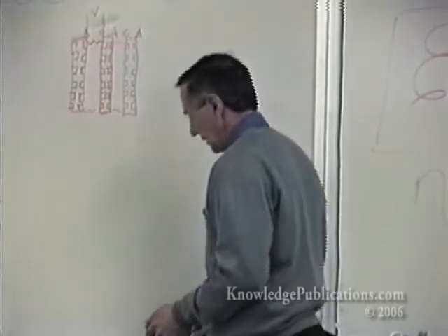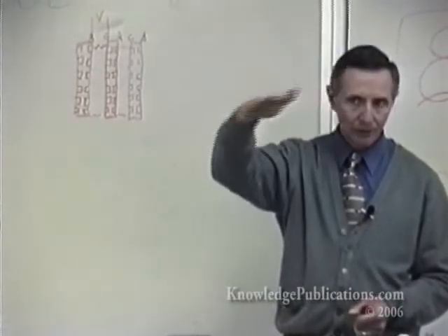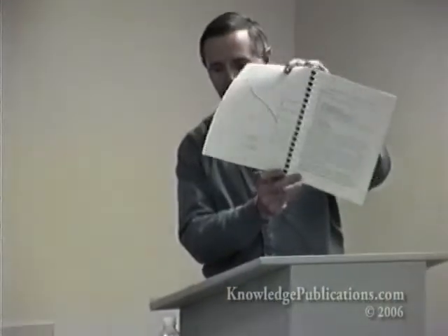The other comment to be made in that regard, and I think this is an important one, is that you can control the voltage drop by pressure. The higher the pressure, the less voltage drop. You can overcome some of these effects that are stealing voltage. We're still on this graph, analyzing this graph. So increasing the pressure of the air would decrease these losses. Increasing the pressure of the hydrogen, which you'd like to do in conjunction with the air so you didn't have a pressure imbalance, I should say, is what you would match with a higher air pressure to get a higher voltage. The slope on this curve wouldn't be as steep.